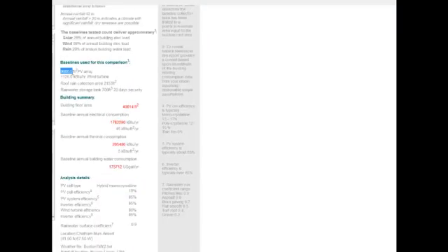In this case, we have about a 10,000 square foot PV array. So this is quite large, of course. But for this climate, we start to look and see, all right, based on our building consumption, this is how much we could offset that consumption with this size of PV array. And this is a very large PV array. So we may decide that this option for the site may not be the best option.